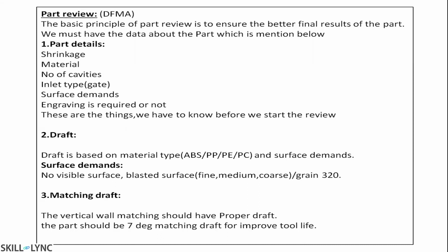What is draft? In order to get the plastic ejection, we need the draft. A part with a lesser draft won't have a good finish. It will have scoring marks. The part with more draft doesn't need much ejection pressure. Always design the plastic with good draft.